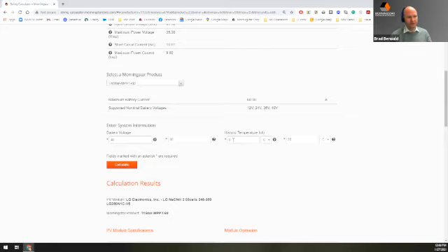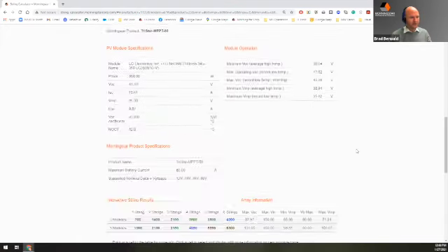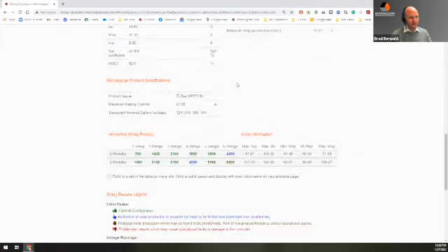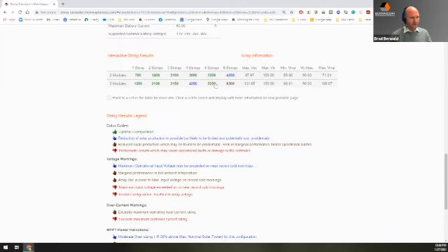And then, of course, you get your historic low and your average high temperatures so that we can account for the changes in the voltage. And when you do that, you get a nice configuration. This is something you can easily print, and then you can hover over the various configurations of the array in order to make sure that your system is optimal. It's optimal with a little bit of power clipping.